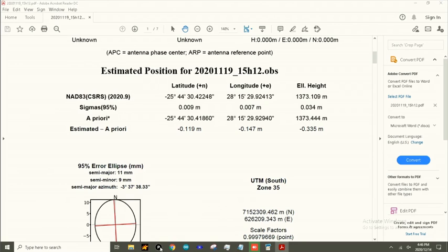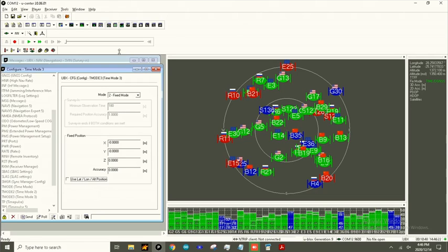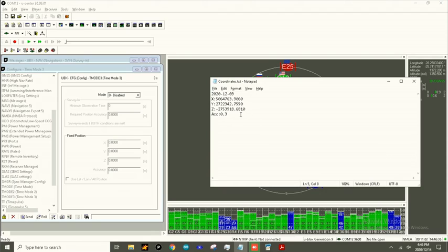So going back to u-center, for now I will just be reverting the receiver to its default configuration to ensure that we start with a clean slate once again. I already have the ECEF coordinates for our own antenna. These will still be updated in due time once we get more accurate coordinates, but these will just be used as an example for now for our configuration here at Engineering 4.0 at the University of Pretoria.